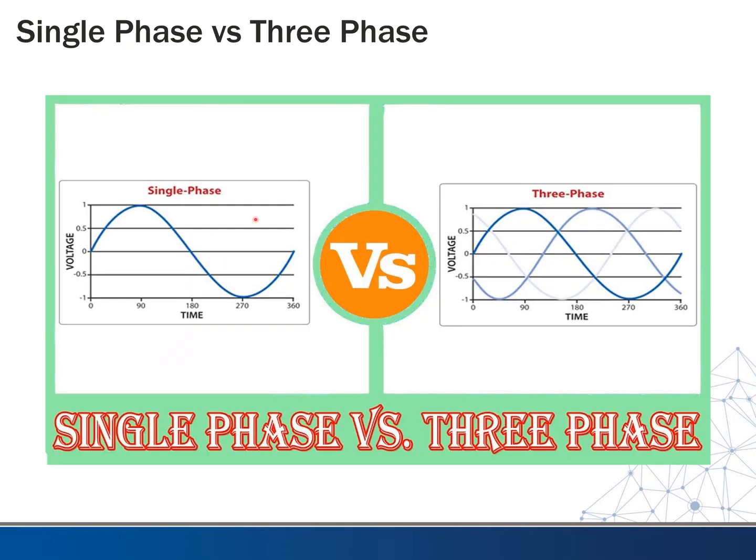Another thing worth talking about quickly is single phase versus three phase. In our houses, we always have single phase. So we just have one phase conductor that will alternate between the maximum and minimum. It's usually 240 volts. Or if we go in between the neutral, it's 120 volts. The potential issue with this is, if you're running a motor and you've got a pretty good load on the motor, you can see that there's 3 times in a cycle where there's 0 power being delivered to the motor.